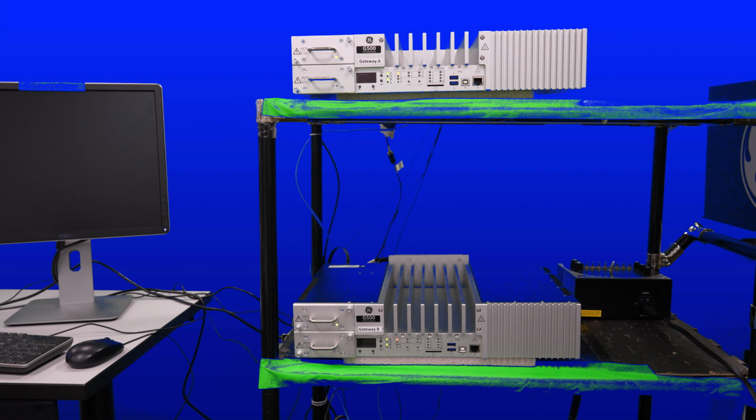If you watch the LEDs on the G500, what you will see is the network connection is healthy and blinking. And also you will see the first two LEDs: the top one is green and the second one is off. So steady green and steady off. That tells us that at this moment, they are in a single setup, which means they're not redundant, but they're both healthy, up and running, and in a single setup. All right. So next step, we're going to set up the active IP address.